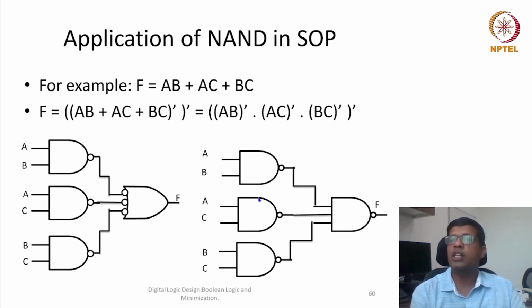That's the reason we can always go for sum of product expressions: if we have a configurable chip with two arrays of NAND gates, then these two arrays can be utilized to design any kind of configurable circuit. We'll discuss the details of how that circuit would be designed some time later in some other modules.